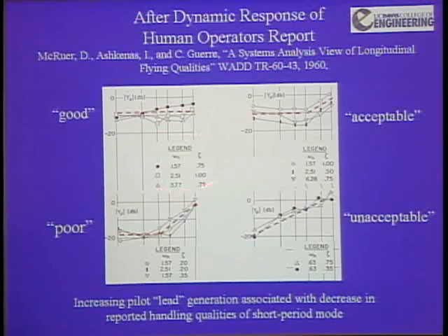And what they were doing was taking the short period dynamics of an aircraft and varying the undamped natural frequency and the damping ratio of the short period mode, putting the pilot in a very simple simulator, having him fly it, and asking him what he thinks of it, how difficult it was. If the pilot acts like a pure gain, that is, his Bode plot amplitude is flat, he said, that's good.